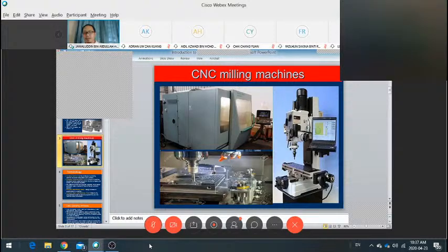Okay. And at the end here, you can see this is also a motor. It will rotate and cause the screw under the table to rotate. They will move the table left and right. Here also you can see that there is another motor. This will help move it in this direction. So the rotation of the motor will cause the screw to rotate, and that's how the movement of the table will be controlled, by controlling the motor.